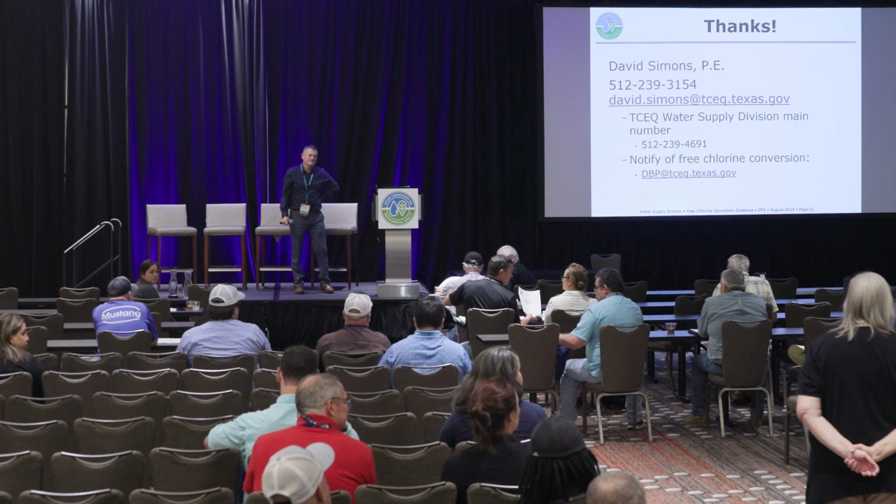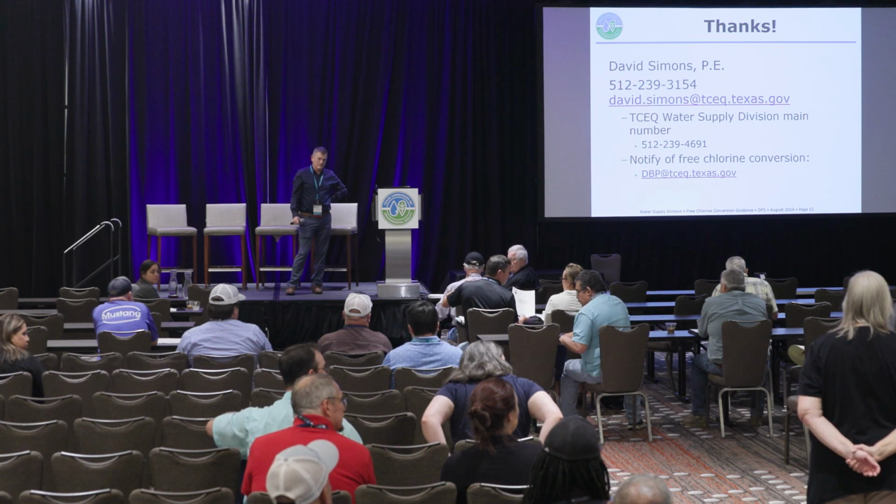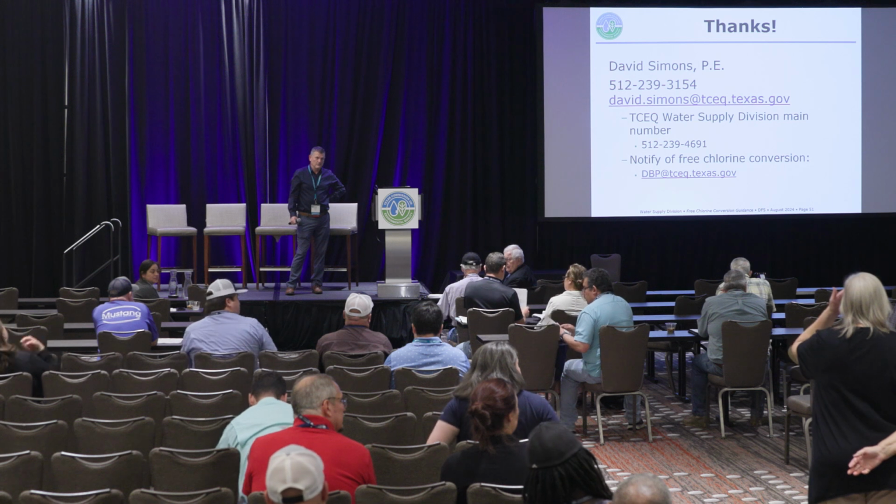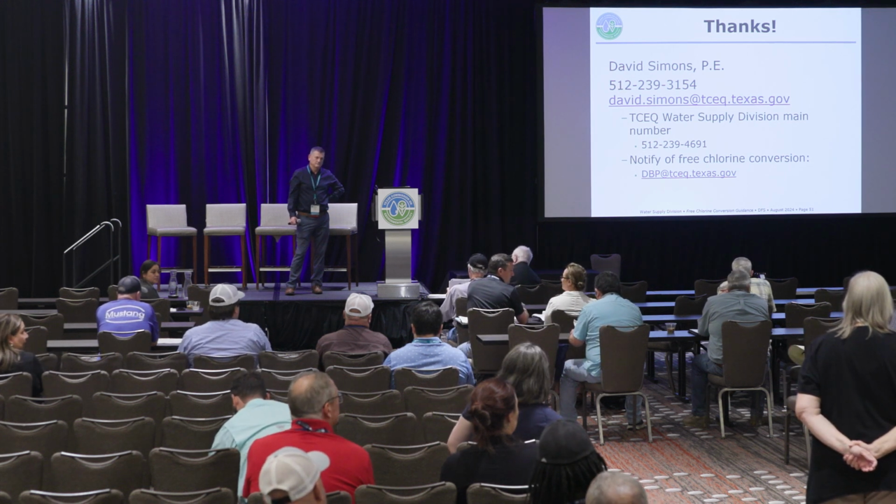For those of us that are purchased water systems, and our treatment plant does the conversion for us before it gets to us, do we still need to notify TCEQ that we're going to go through a conversion? Typically, when your wholesaler notifies TCEQ, they will ask who your wholesale customers, your purchasing customers, are that are also going to be taking part in this. If your wholesaler doesn't give that information, it still might be a benefit for you to at least ask our DBP team, hey, do you know we're going to do the free chlorine conversion at the same time that so-and-so is doing theirs? It wouldn't hurt anything to do that. Okay. Thank you.